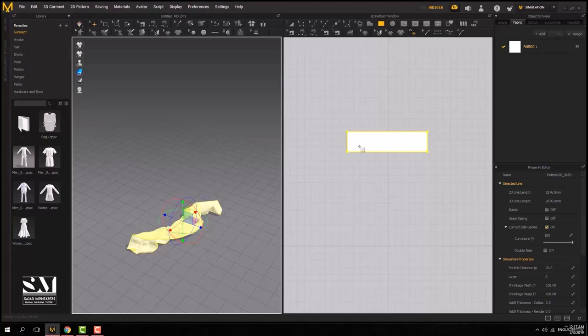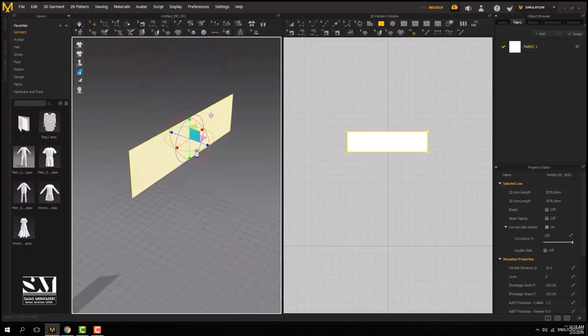Now, if you need part of your pattern not to be affected by gravity, what should you do? You must freeze it. I think we talked about that in previous sessions. I can undo with Ctrl plus Z to return to the state before simulation. But if you've progressed through many steps and undo can't take you back to before simulation, there is a tool called Reset 2D Arrangement. If you select your pattern and then click this tool, it removes the simulation effect and returns it to the pre-simulated state. So that's the usage of this tool.